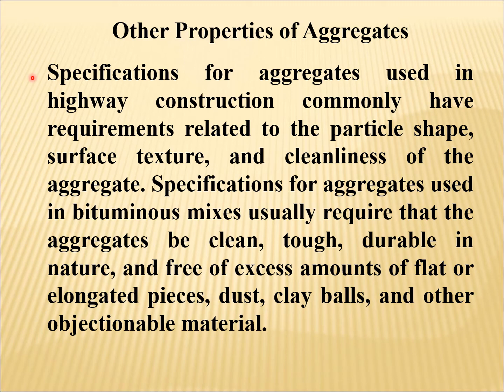Specifications for aggregates used in highway construction commonly have requirements related to the particle shape, surface texture, and cleanliness of the aggregate. Specifications for aggregates used in bituminous mixes usually require that the aggregates be clean, tough, durable in nature, and free of excessive amounts of flat or elongated pieces, dust, clay balls, and other objectionable material.